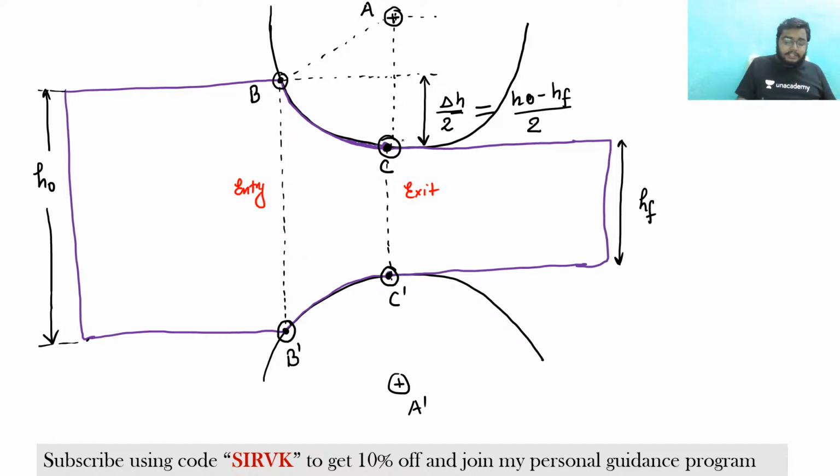I have explained these things. So what is this distance? This is R, the radius of the roller. This is also R, the radius of the roller. If I write this as point C, then the whole AC is R, the radius of the roller. Let me write this as D. So AC is R. What about AD? Can I say that AD will be nothing but R minus delta H by 2?